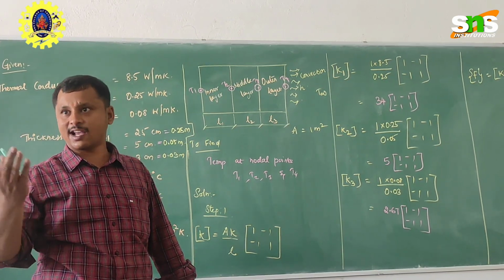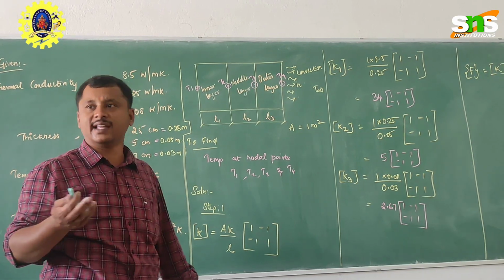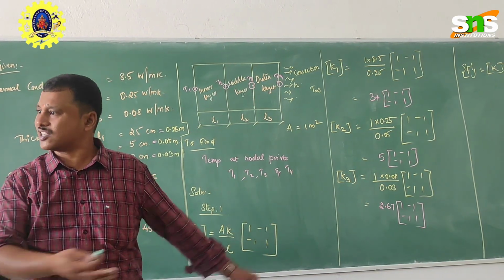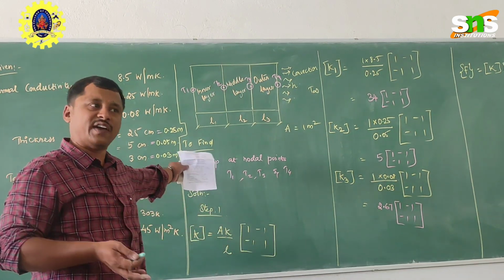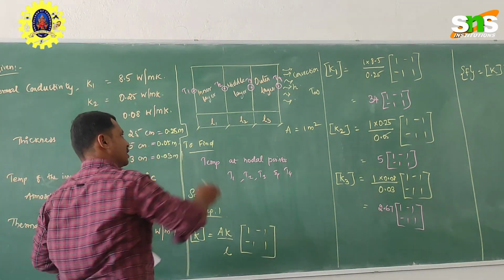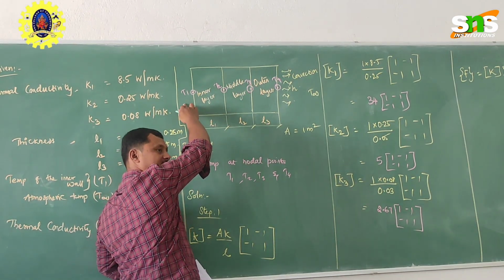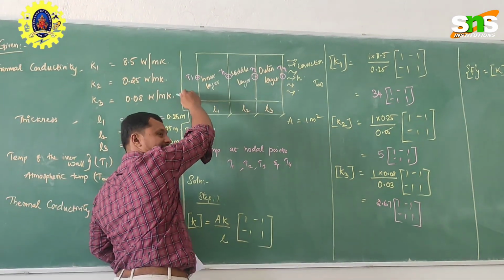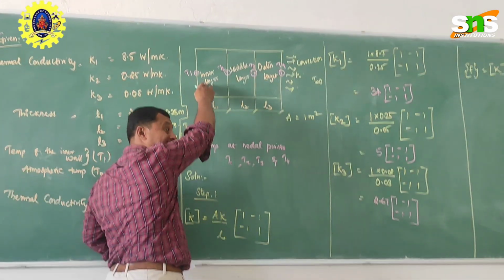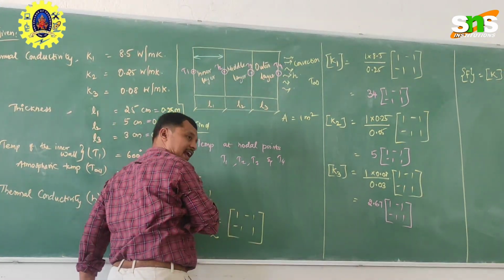Example, a furnace is used in a foundry to melt metals. So this is the problem you are solving using finite element. Here, in the inner layer of this furnace, the temperature is in effect and the material is melted. That temperature is conducted here, so here it is conduction.